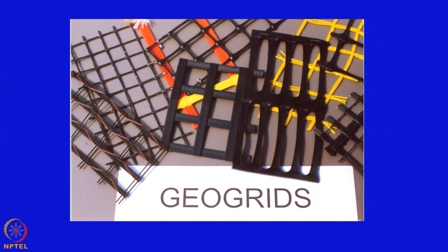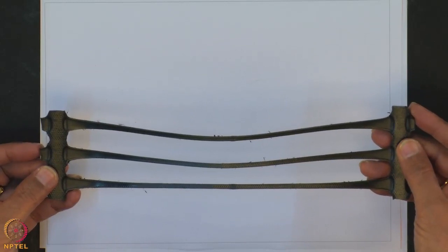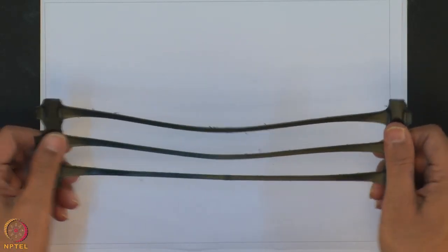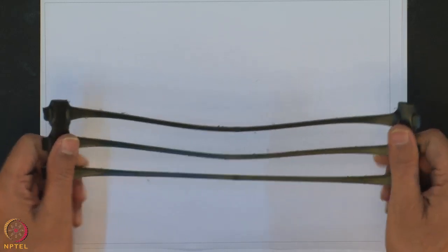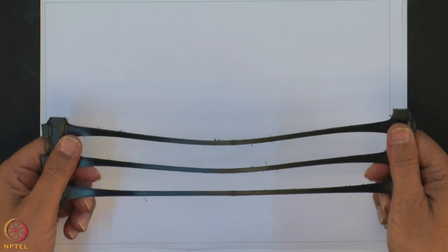Next, this is the geogrid material. This material has a uniaxial geogrid and also the biaxial geogrid. This is the uniaxial geogrid. Okay? And this acts as a reinforcement, and you have to determine the tensile strength in the machine and cross machine direction and the corresponding elongation.